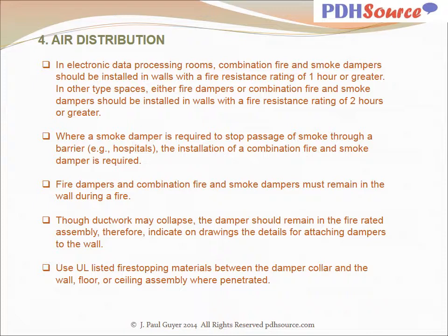Fire dampers and combination fire and smoke dampers must remain in the wall during a fire. Though ductwork may collapse, the damper should remain in the fire-rated assembly. Therefore, indicate on drawings the details for attaching dampers to the wall. Use Underwriters Laboratories listed fire-stopping materials between the damper collar and the wall, floor, or ceiling assembly where penetrated.